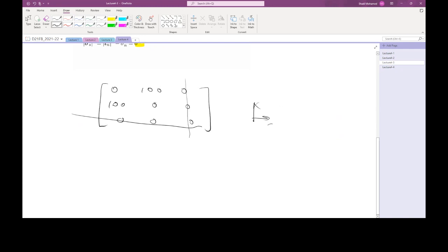This is x1 and x2, and this is the square, which we have been talking about for a while now. Now, this is sigma 1, 1, this is sigma 1, 2, this is sigma 2, 1, this is sigma 2, 2, right? I'm going to draw them. So sigma 1, 1 is 0, so you don't have anything happening in this direction. This is 0 there, right? If you look into sigma 1, 2, this is active on the plane number 2, and the direction is parallel to 1. So this is 100.